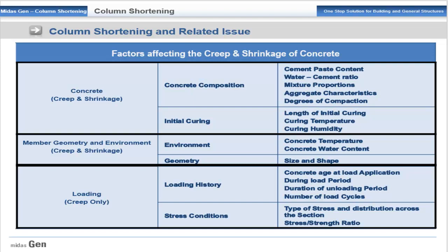So the loading history and the stress conditions, that is concrete age at load application, duration of loading period, the duration of unloading period, number of load cycles, types of stresses and distributions across the section, then stress upon strength ratio are the factors.